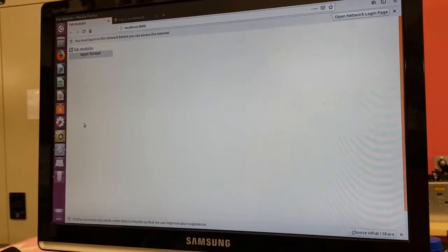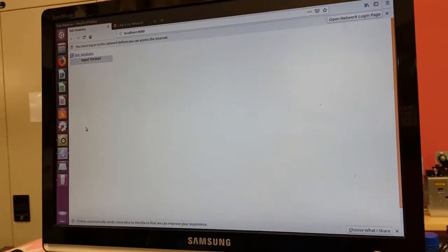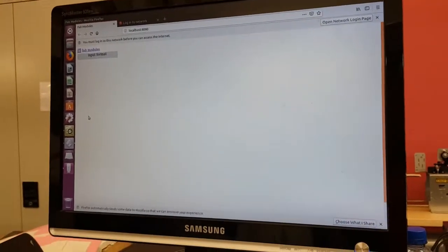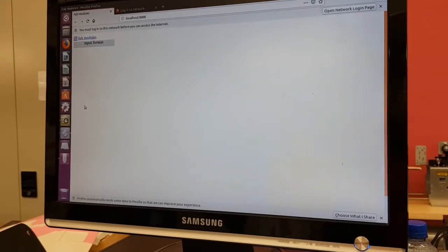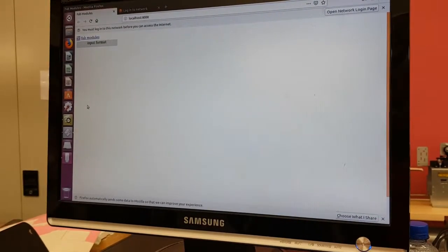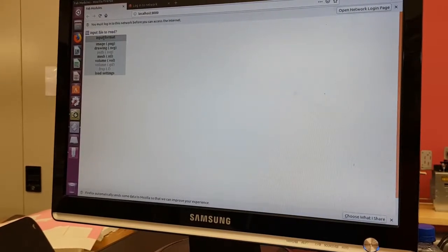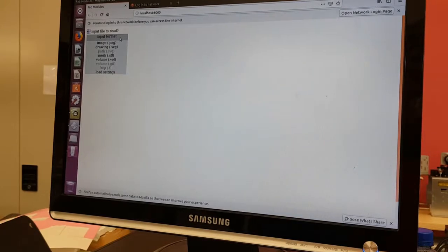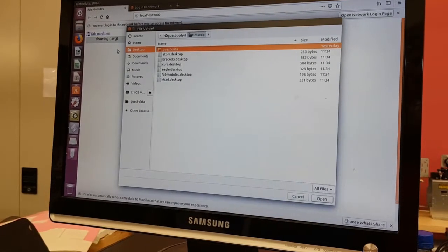It's a web-based, I guess, like CAM program. It's made in-house within the Fab network and is used to drive a whole bunch of machines, not just the vinyl cutter specifically. So it also drives the PCB mill, and you could use it to run the shop lot and other weird and wonderful things as well. So if you hit input format there, you'll see it asks us for a number of different files. PNGs or SVGs are probably the two we're looking for, our 2D vector files today. So you can open your SVG file. Hopefully you remember where you saved it.